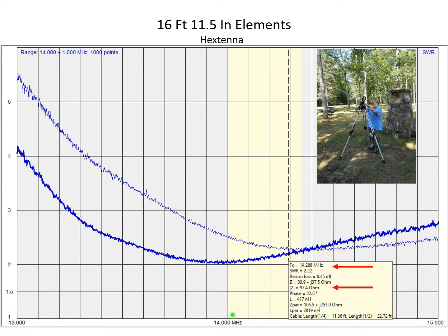So we ended up with a resonant frequency of about 14 megahertz, which is a fairly typical target that a lot of these antenna manufacturers look for, because this is the CW range of the band. In this case, since we're wanting to operate the transceiver in single sideband mode, we're targeting the middle of the general band for single sideband, and that would be 14.288 megahertz. So what we want to be able to do is figure out a way to move this point over to this frequency so we get our lowest SWR in the middle of the band that we want to operate.